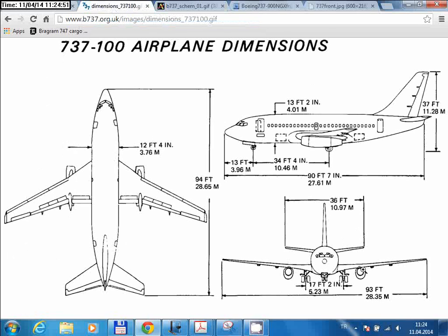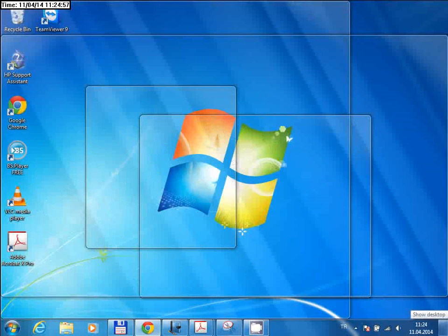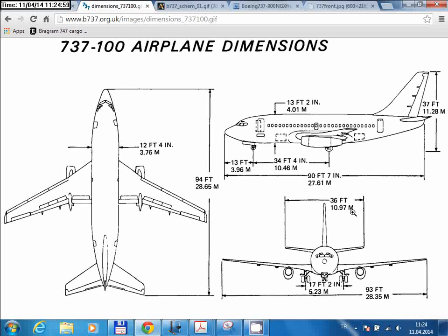So it was using a turbofan engine with a certain amount of inlet area. Then in the newer generations, to increase the efficiency of the airplane, they replaced the engines with more efficient engines. And more efficient means what I just said: more efficient means it can take more air in and give it a smaller acceleration.